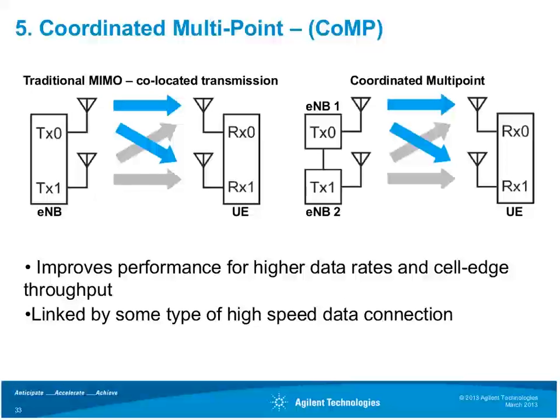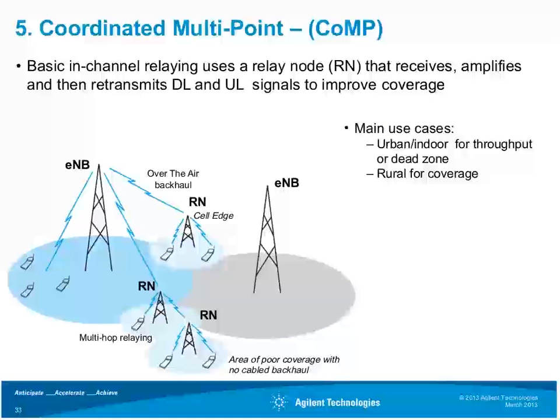Within the confines of a single device, whether a UE or a base station, the sharing can be accomplished on a chip or between modules. But in cooperative MIMO, there's distances maybe up to even several kilometers. So sufficient backhaul transmission bandwidth with the necessary latency, can't have a delay, is a considerable technical challenge.